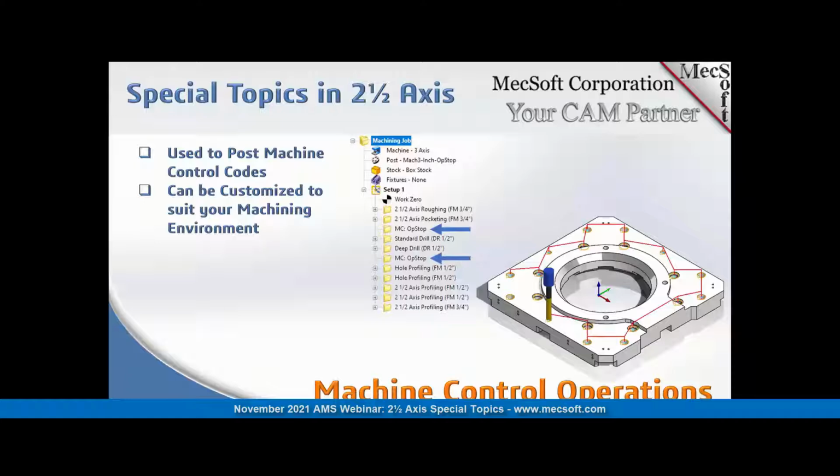And you can use one of 4 different machine control cycles, and you can define those for whatever type of code that you want to insert into your posted code. And as you can see in the setup, you can define that machine control cycle where you want it to appear in the setup sequence of operations. So Joe's going to be going over that as well.